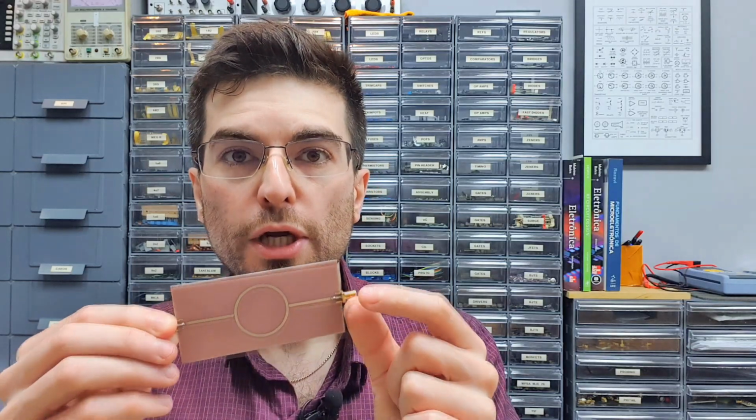And this is because the electrical length is greater, and the dielectric constant, the constant that we need to measure, is what defines the relation of propagation speed for the electromagnetic wave. So what happens is that the electrical length looks bigger than the physical length because the speed of propagation is reduced by the substrate. And in practice, it is this reduction in propagation speed that we need to characterize so we can use this constant in future designs.